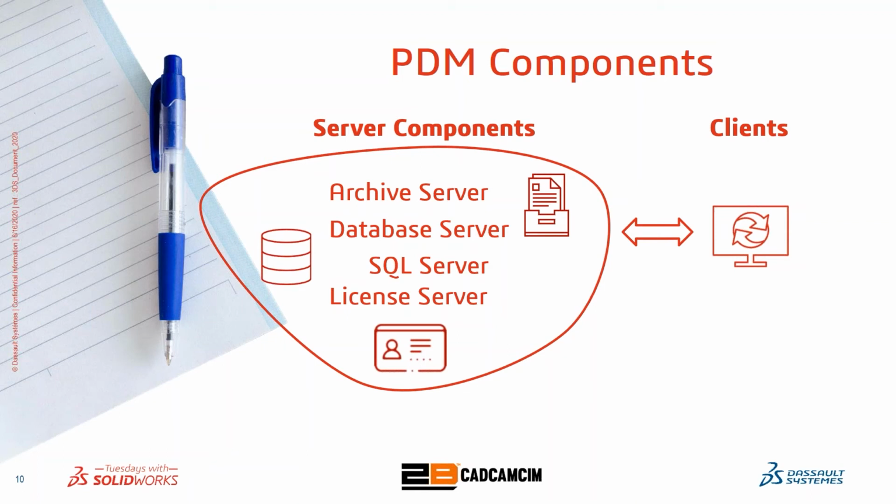Also, at every client installation, we have the admin tool, which enables you to administrate your PDM file vault. And we will go through different options using the admin tool in this presentation. By the way, you can always open the admin tool by going to Start in your Windows and typing the word administration.